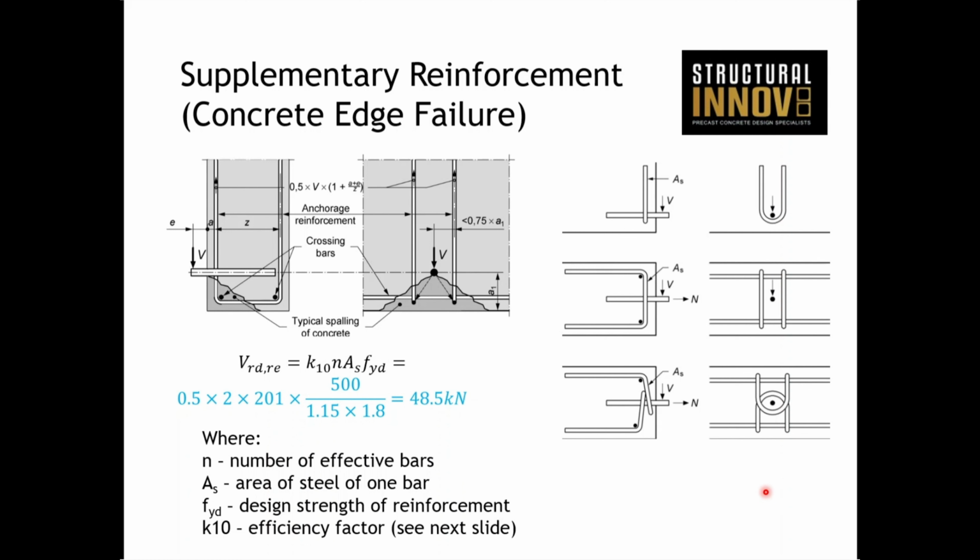Often you might have to tilt it in the factory to get a look at the other face for touching up, or if there's other additional works to be done. And when they tilt it back down, there's no guarantee to tilt it back down the same way. So depending on how you're lifting, you have to account for both faces being face up, and then you're covered in terms of your design. But only one of these is effective at any one time.